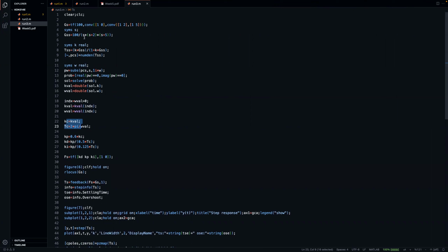Now, theoretically, the Ziegler-Nichols method is actually for cases where PID controller design is quite hard, like nonlinear systems, or probably also very high order systems. That could also be an application case. But this is a powerful tool if you think about it, because you don't really care about the whole system. You just look for the marginal stability and you come up with certain values from it, and then you use them from a table.